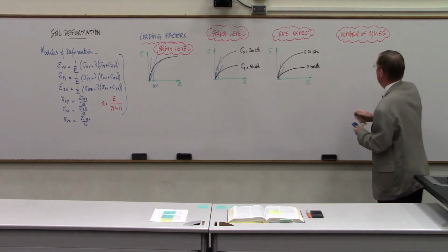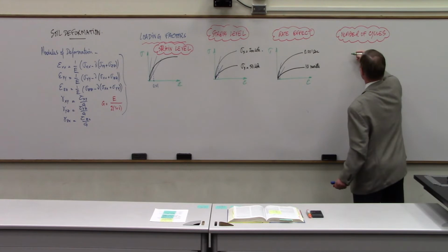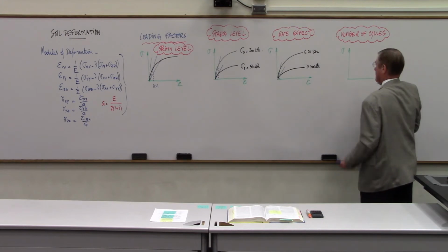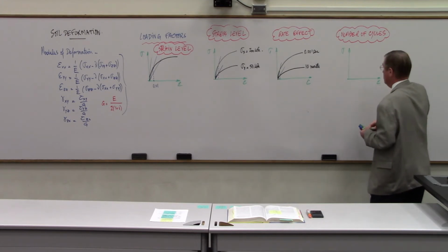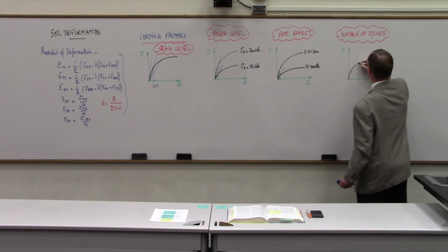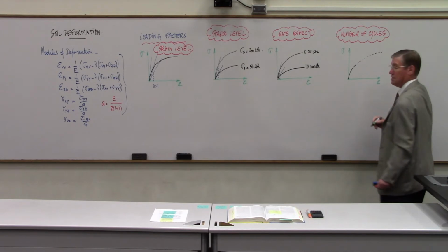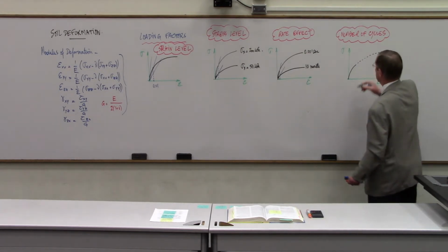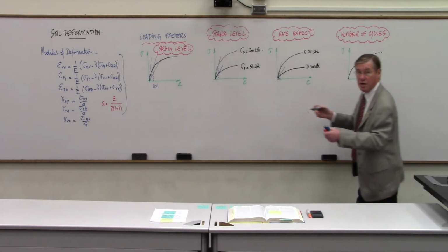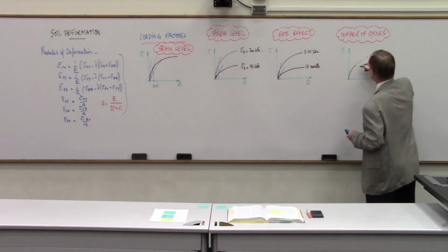You can imagine that if I take a soil sample and I do a triaxial test or any other test, and I start loading the sample, and if I were to continue, it would go on something like this. But here I say, oh, wait a minute now, I've got a platform that's going to be subjected to a lot of hurricane waves, maybe 1,000 of them. Then I'm going to have to simulate this by doing some unload, reload cycles.